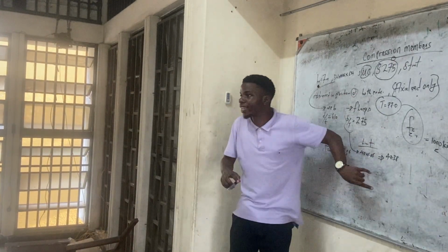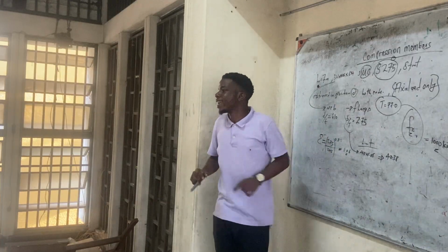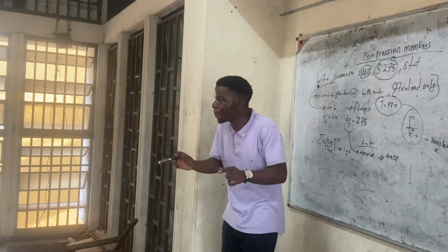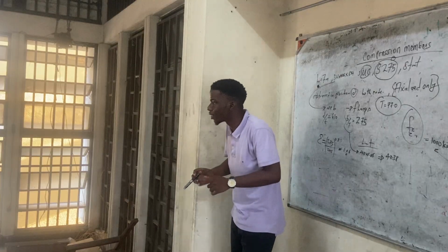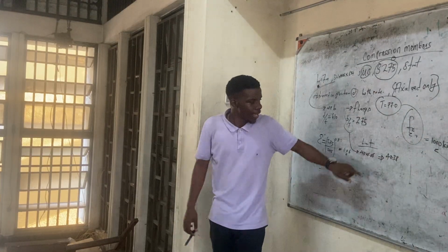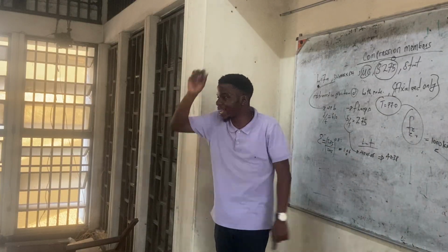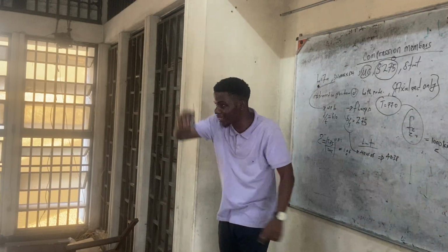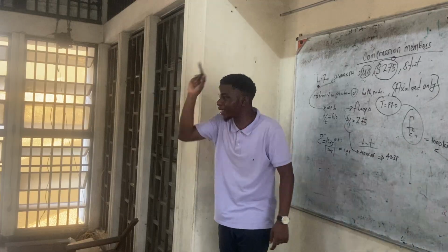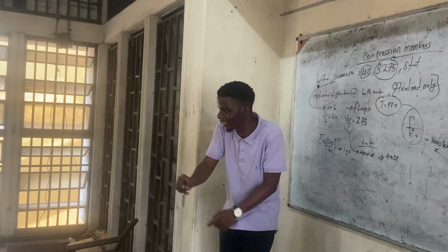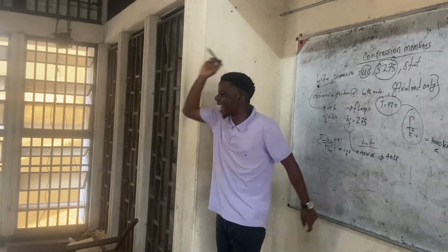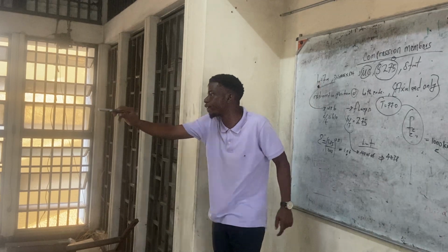Now, this class 1 that we got here was semi-compact and it was the weakest, right? We're lucky that it's the weakest that we have there, because eventually it's still the weakest that we will use to classify the entire cross-section. But what if class 1 was plastic? And for class 3, we don't know what the classification of the web is.